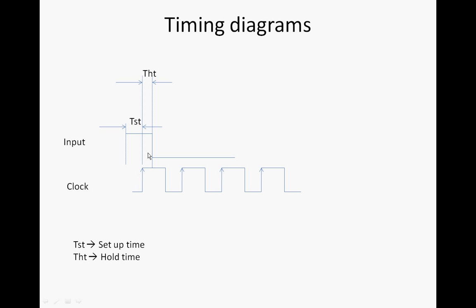So what is the hold time? For my circuit to operate, provide a reasonable output and charge the output capacitance, at least this much amount of time the input should be present so that the valid output corresponding to this input appears on my terminals.